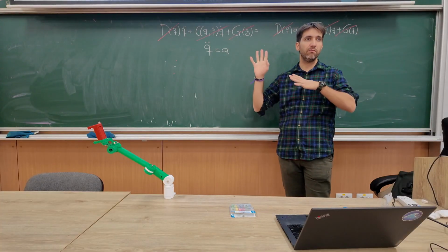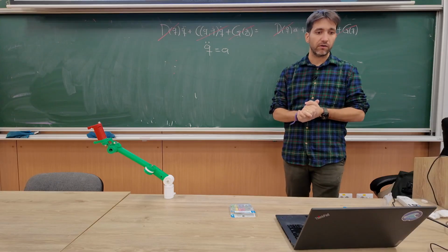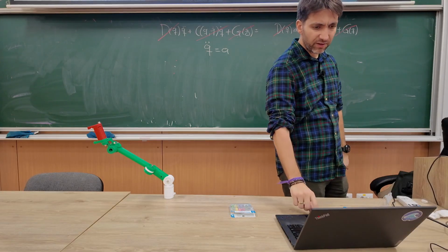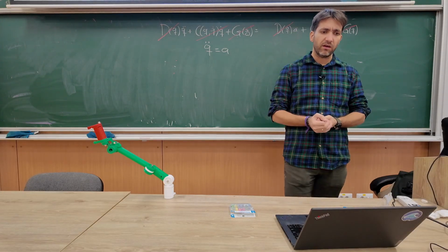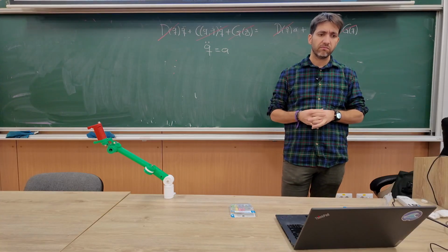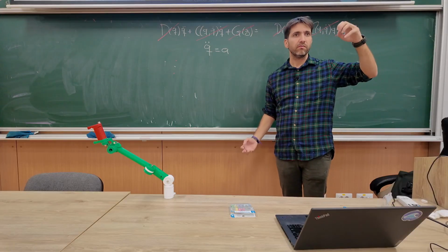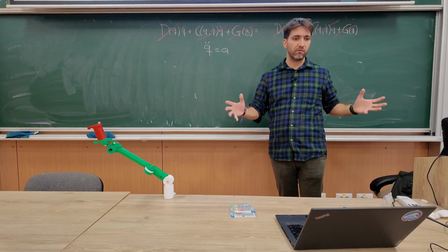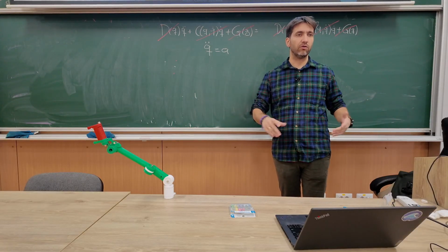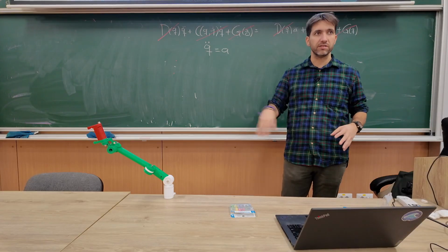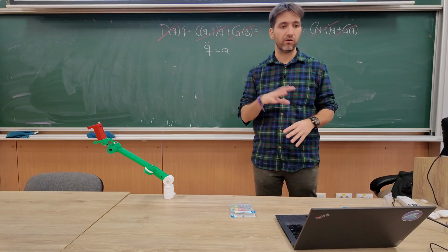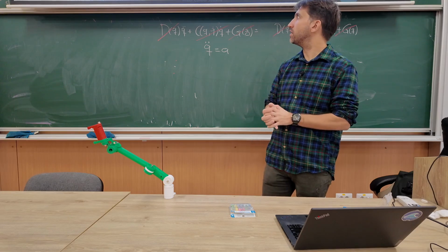And this is a MIMO controller, because this is basically state feedback, because I take the states, which are positions and velocities, right? And I take all of them in one go. I have one matrix for all of them, and I control the whole system, all the inputs and all the outputs at the same time.